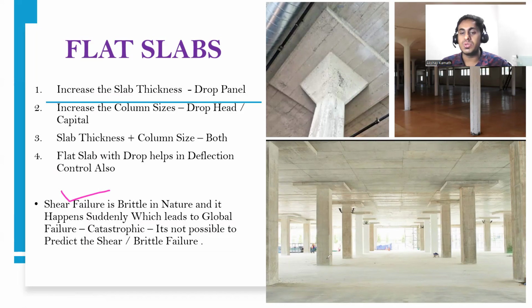And also when you do the de-shuttering, initially we give props like this for support, but usually when we do the de-shuttering, we allow these props to remain there for at least, let's say, 25 to 28 days, and after that we proceed, since this area is a very critical element for us. So that is the reason we try to give a lot of props here.